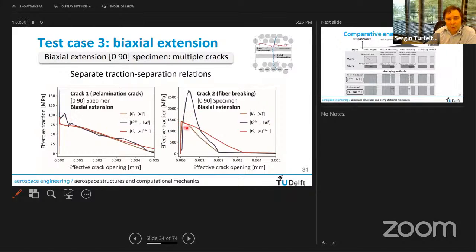And towards this one, on the other hand, this is a much larger value, because this involves the fiber cracking. And again, this kinematic space method overpredicts the strength quite significantly, just to match the energy dissipated. Whereas the approximate method here underpredicts the energy dissipated. So this one does predict the energy dissipated. The kinematic space method predicts the energy dissipated exactly, because that's the definition, and it gives you a quite reasonable value for the strength as well.